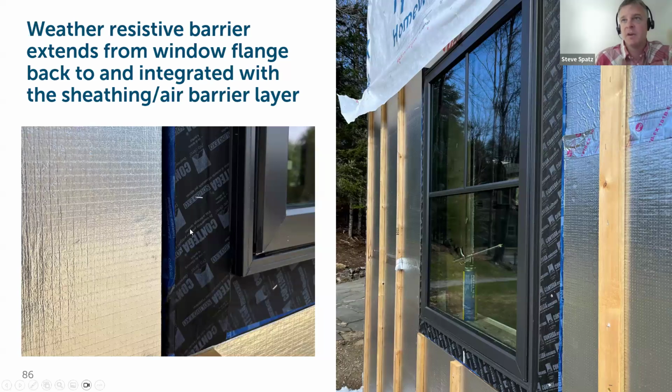So in this scenario here, we've got 3 inches of continuous insulation with a built-out window buck that planes out with the face of the continuous insulation, but all of the flashing details from the face of that window at the plane of what the wall will see from the exterior, everything is flashed back to the WRB, which is behind that continuous insulation layer. So the taped foam board in this scenario is really just to protect the tape or protect the foam board itself.